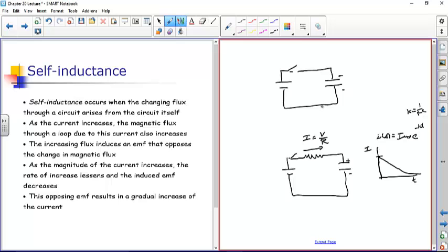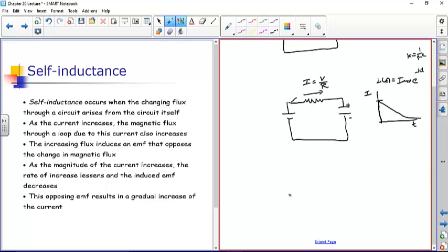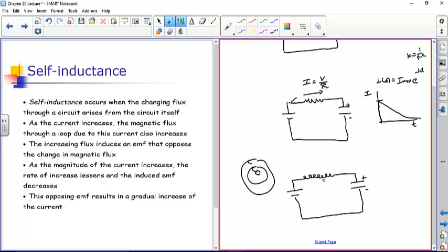Now, nature does not like discontinuities, meaning you go from one value to another value almost instantaneously. So we're missing one situation. In any circuit, you can design an inductor into the circuit, or just a wire is the simplest kind of inductor, because even around a wire we create a magnetic field. An inductor is like a solenoid, and it gives you more inductance, so it causes this phenomenon to happen to a more significant degree, but just a wire itself will act as an inductor.